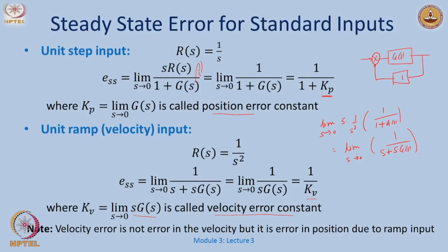Okay. So, if I have a feedback loop, I just draw it here again. So, reference plus a minus y of s and so on. Okay. Right. So, if the input or the reference is a step, then there will always be an error. So, if I just take an underdamped, whatever kind of system, and look at the steady state curve, this is my desired value, my actual value might just be somewhere here, right. So, this is the steady state error.